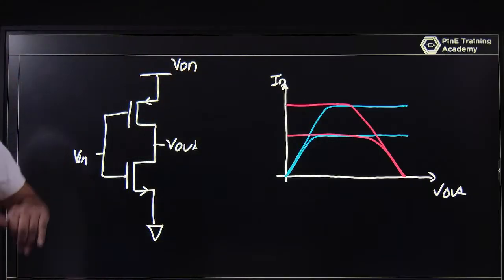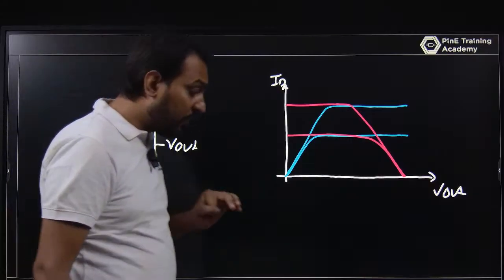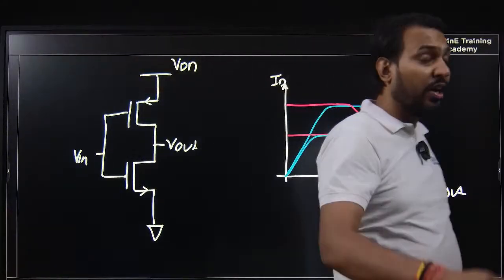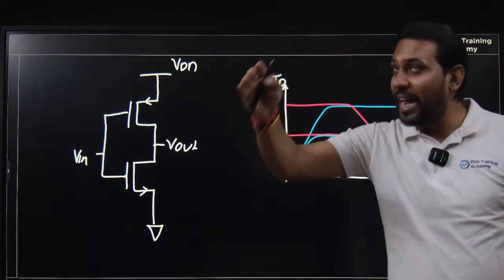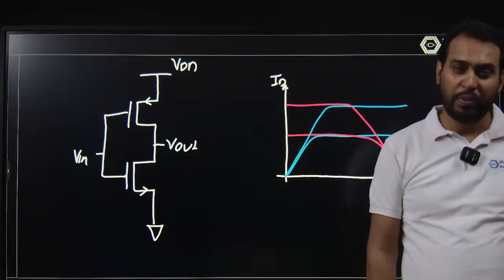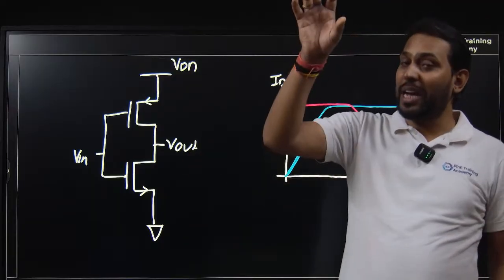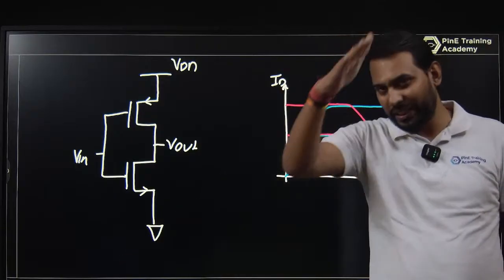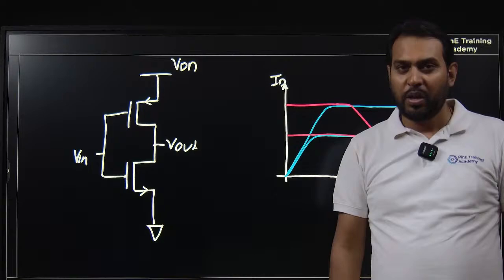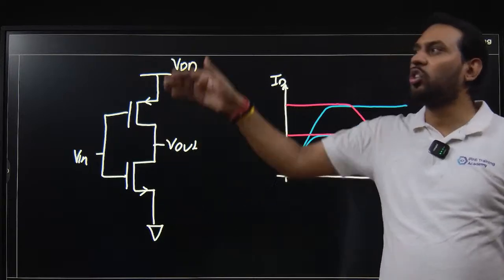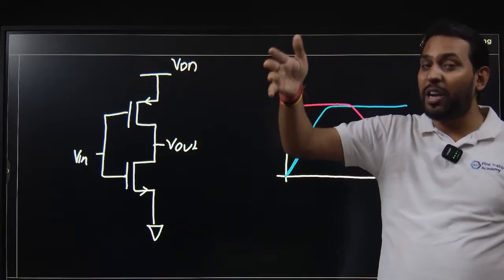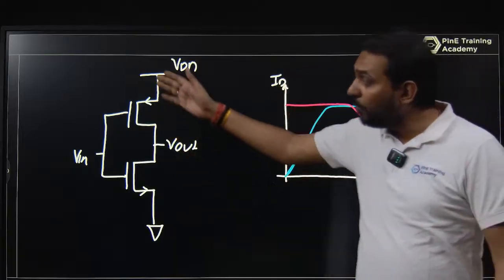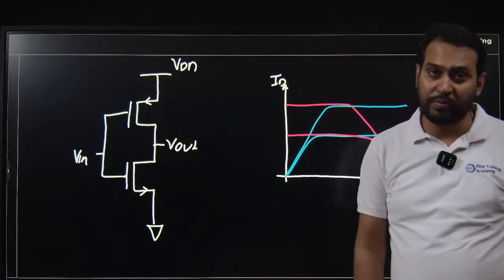So with the resistive load, you have a DC operating point as a straight line with a negative slope. If you are using a diode-connected load, that is 1/gm1, or 1/gm2. If you are using a PMOS, it also provides that, but it is not dependent on the input. Here the input is the same for both.